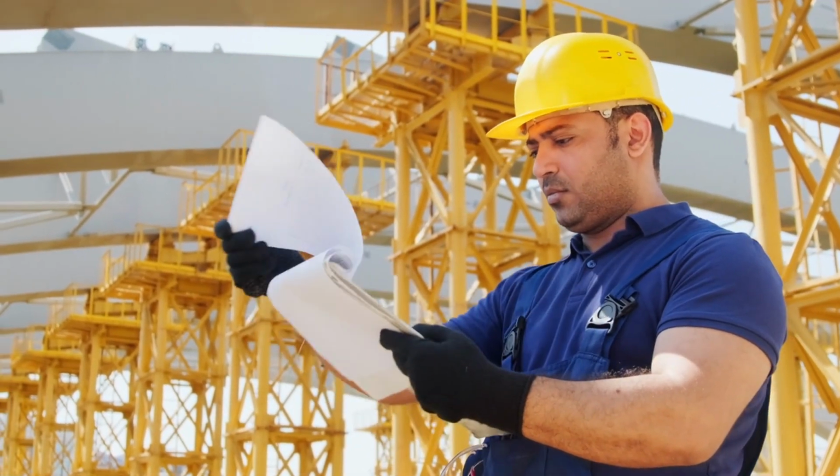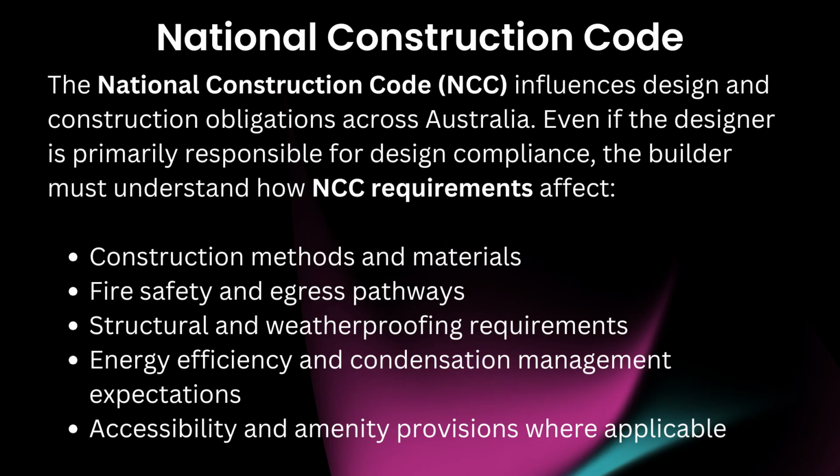National Construction Code. The National Construction Code, NCC, influences design and construction obligations across Australia. Even if the designer is primarily responsible for design compliance, the builder must understand how NCC requirements affect construction methods and materials, fire safety and egress pathways, structural and weatherproofing requirements, energy efficiency and condensation management expectations, accessibility and amenity provisions where applicable.